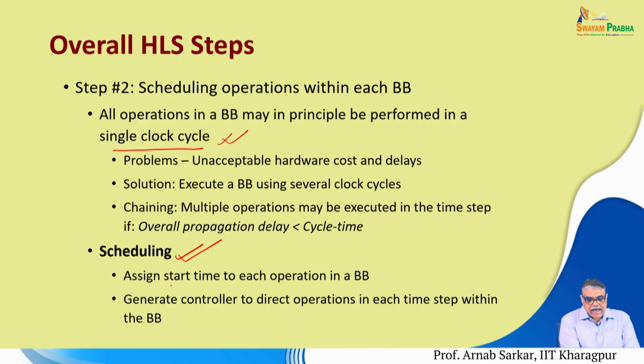Scheduling assigns a start time to each operation in the basic block, and we will take examples and see all these things in greater detail. After you have assigned the time steps to each operation, we have to generate a controller, so that what the schedule has told us, that certain operations should be performed in certain time steps, actually happens in those time steps.